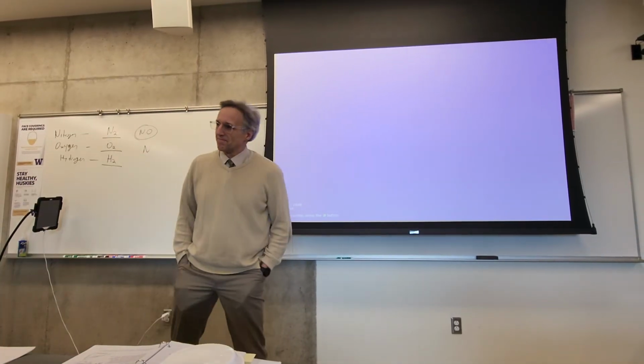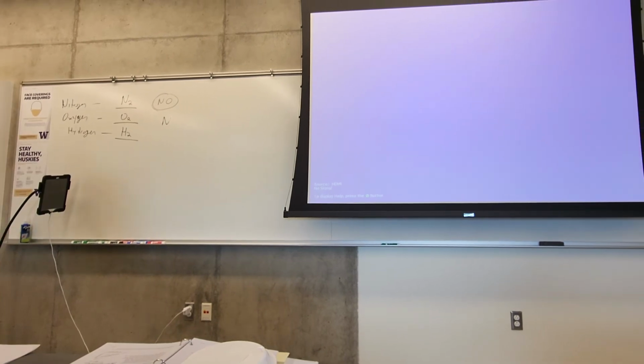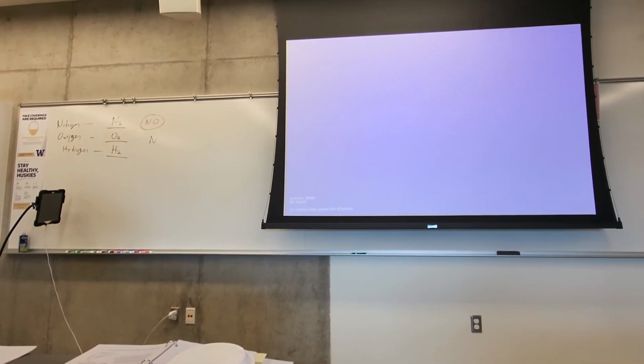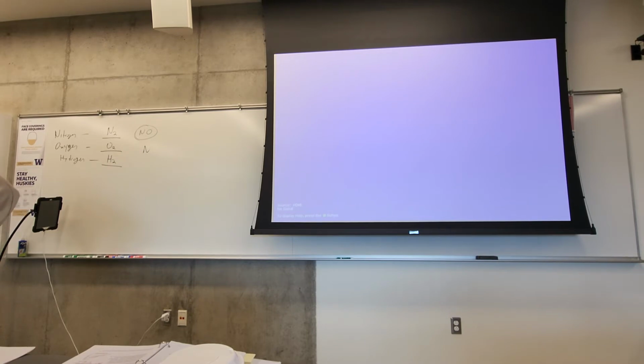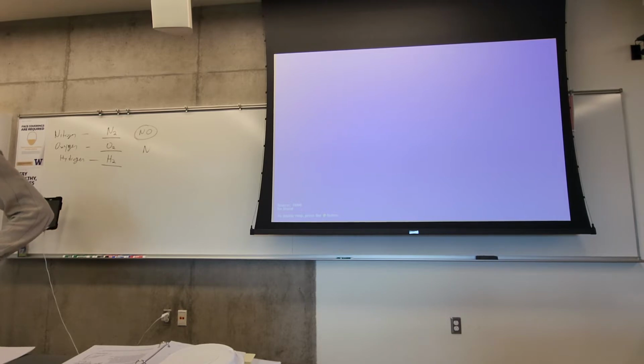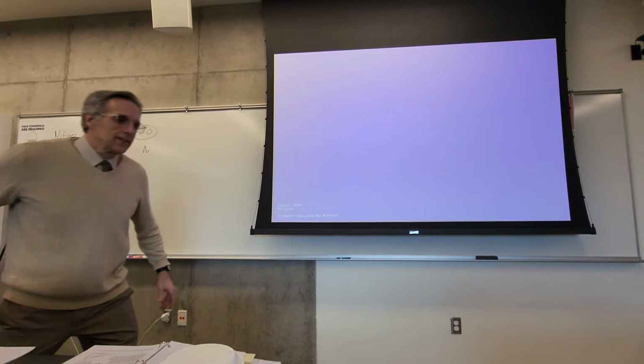Dr. Cole, I wanted to ask, just conceptually, for where it says what is the rate of heat removal, that would be both sensible and latent, correct? So it'd be like the triangle part between latent and then sensible? Okay, thank you. I think that was explained in the video that you posted. Yeah, it's the triangle part, but it's a little bit deceptive because you don't calculate it like the hypotenuse. It's actually the real sum of the sides, QL plus QS. Okay, but it's just represented like a triangle. Yes, sir. Okay, thank you.